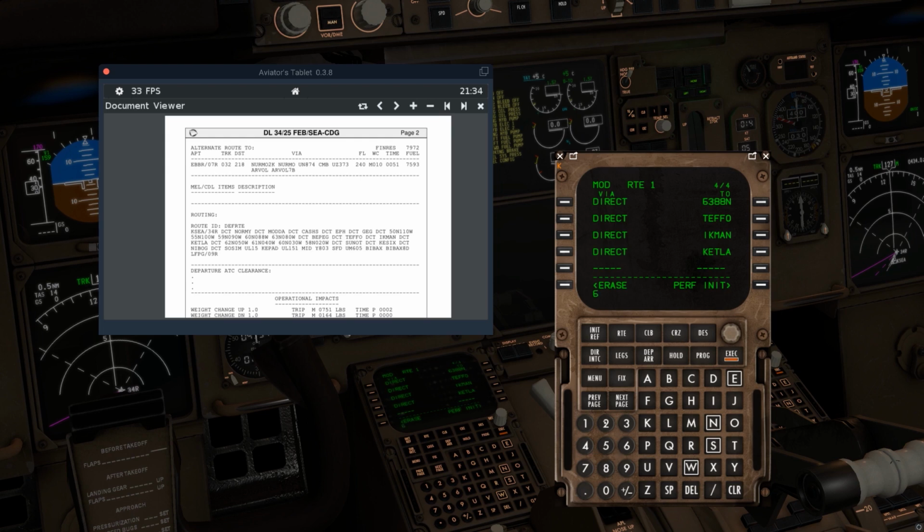Okay, that's 62 north, 050 west. And again, because that 050 is under 100, if that was 150, we would put the north here. And this is just a formatting peculiarity with these FMCs, or the Boeing ones. I don't know how the Airbus is. I haven't tried that one yet.